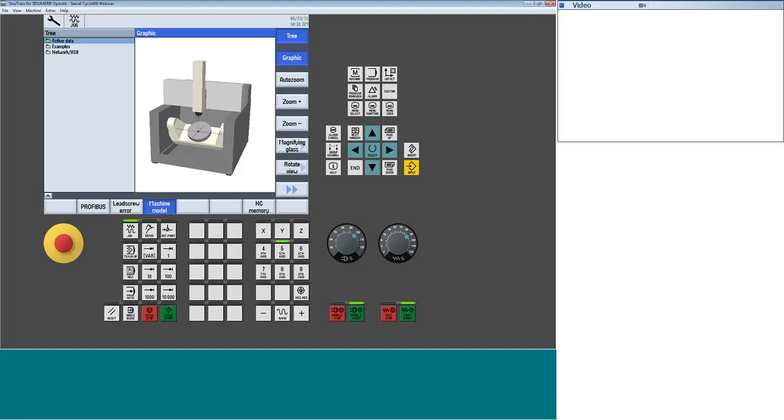Probably the most basic way of zeroing out a machine will be using a direct axis 0 like this, where I'm going in and I'm zeroing it. And that's pretty typical to any machine in the industry today. Usually you have some way of zeroing out your rotary axes. The problem comes in if the machine itself is not managing where the 0 is in relation to the center line of the rotary axes and where the platter is.